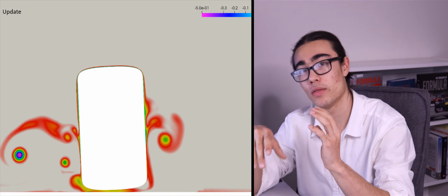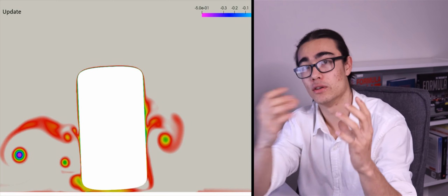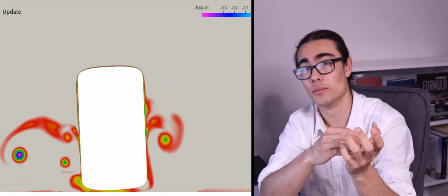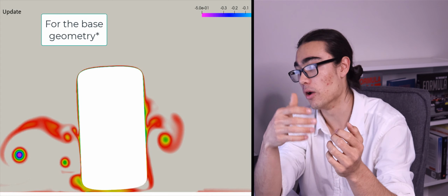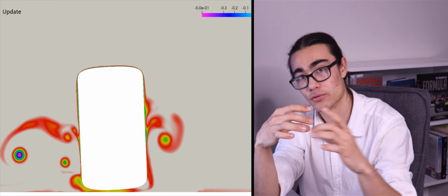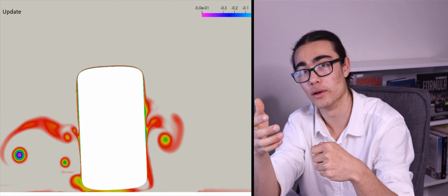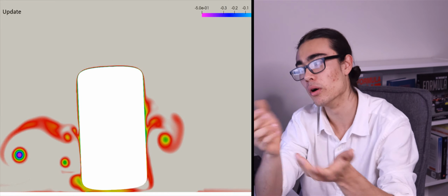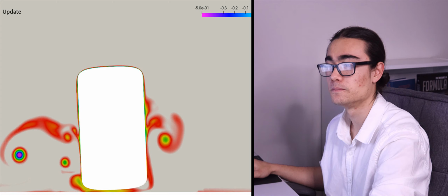We do have to remember though that our loss from the front wing footplate was laterally going to move in further to fill the void behind the front wing, which was more effective, but also originally we just saw how much further it was in, so it doesn't really matter the reason behind it. It was always inboard a little bit more, so that could also be a reason why we're kicking up a bit more squirt in that particular place.